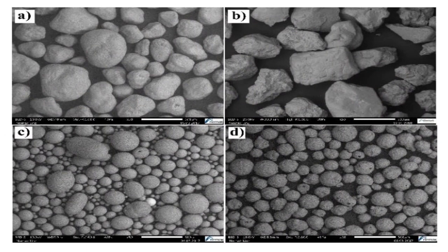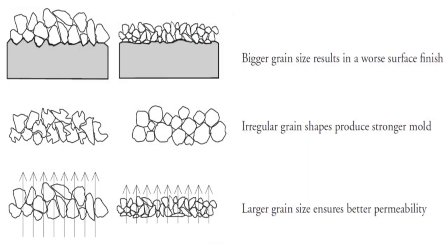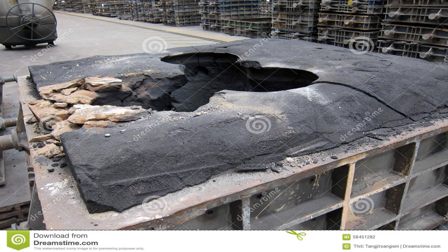Permeability is required where fluids and gases penetrate through the pores. Good permeability of the molds and cores will allow the gases and the steam evolved during casting to escape easily. The molds also should have good collapsibility to allow the casting to shrink while cooling and thus avoid defects in the casting, such as hot tearing and cracking.